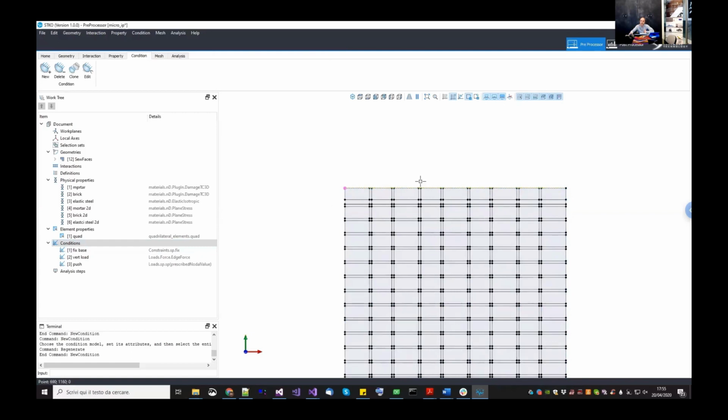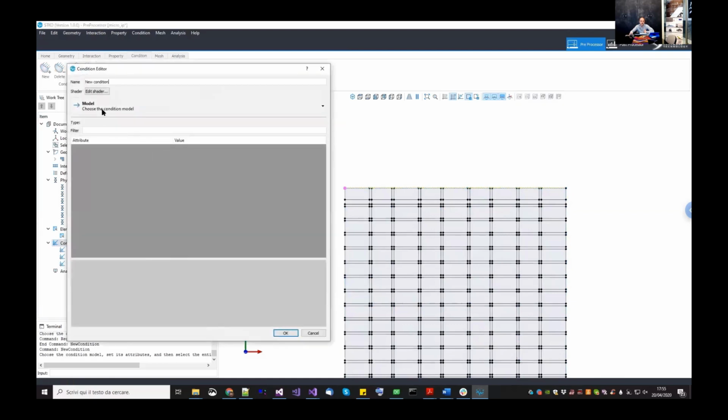So it is not sufficient to use an equal DOF constraint, because an equal DOF constraint will prevent the rotation, but the entire wall can uplift. In this case, we want to actually fix it at the vertical displacement it reached with the vertical load. So instead of using a fix, because fixing it at 0 means that after the vertical analysis, the wall will come back to a 0 position, we want to fix the top at the current position.